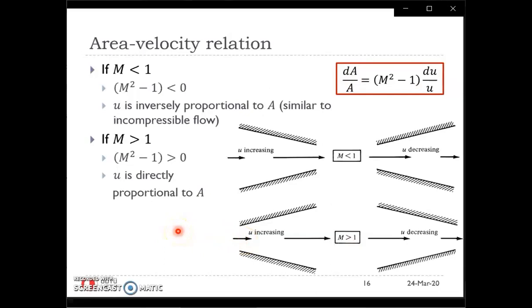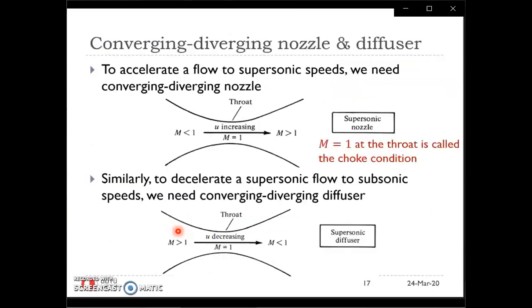If you remember, in our face-to-face classes we also related this to the existence of shock waves. When we were discussing in Anderson, the flow turns towards itself, which actually means if you consider the far away streamline, it causes an area decrease, and for a supersonic flow that means deceleration, so it can only happen through a shock wave.